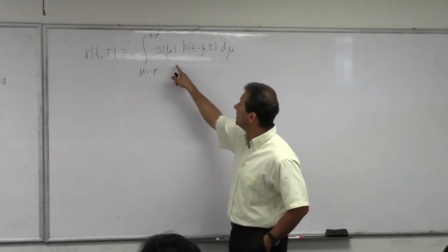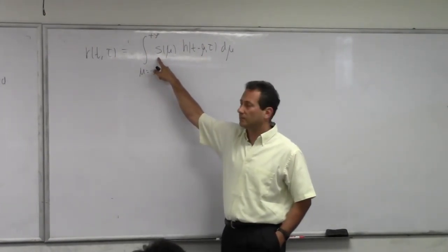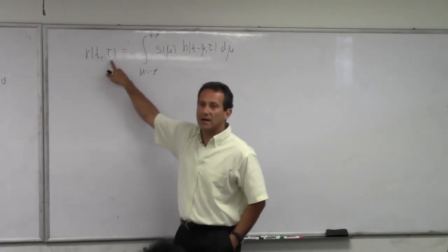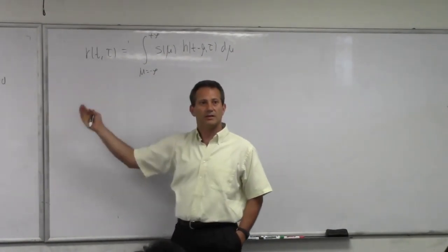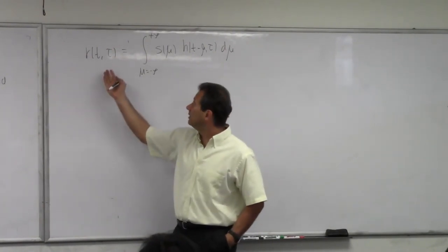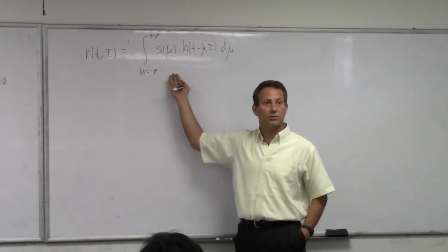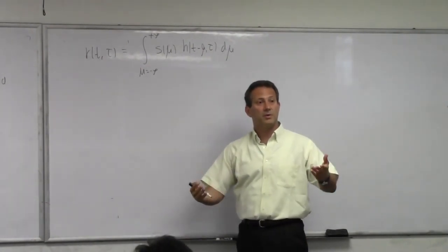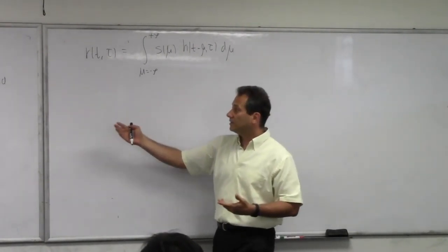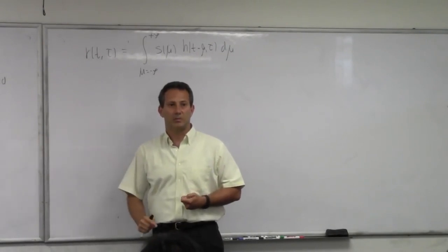Here, what you have embedded is that if I take the same signal, s of t, and I feed it into this channel at two different times, tau, I'm going to get a different output, right? And the input-output relationship is still linear. It's still convolution. But the impulse response of the channel changes over time, and therefore, even the same input fed at two different times will give me different output.